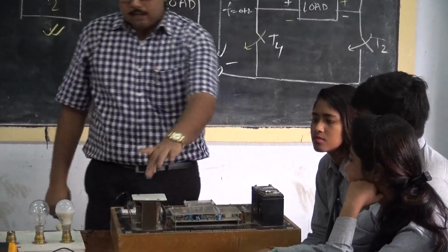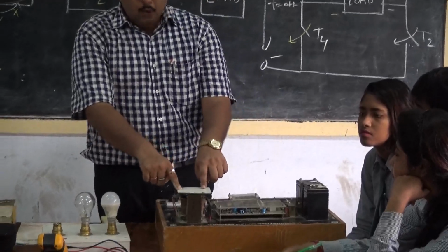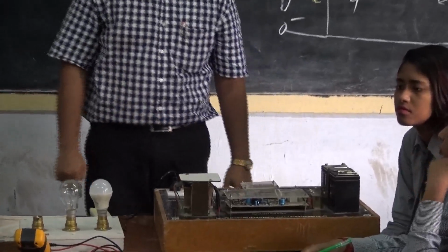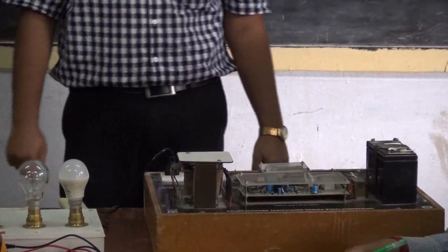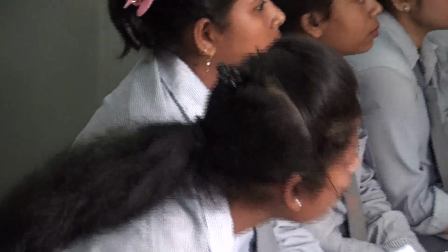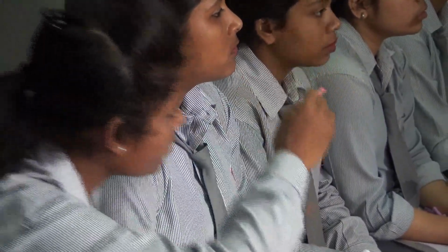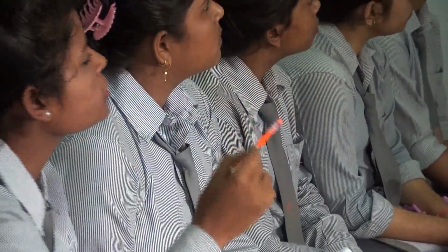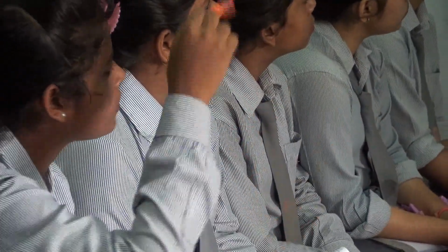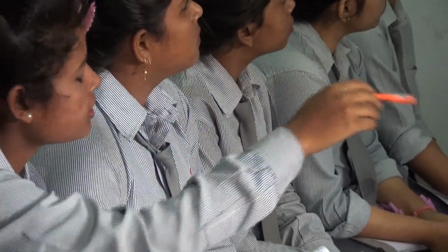Okay, and here it is not written, but it is a step-up transformer. Why is the step-up transformer needed? Anybody can tell? Why is this transformer needed? Yes, why? Our load is 220 volt. Yes. And for the inverter we don't get that 220 volt. So for the load we need that 220 volt AC. That's why we need the step up.